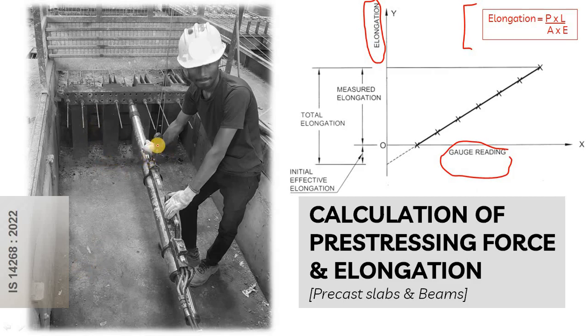Here in the left hand side figure you can see the pre-stressing gun that is used, and these are the strand wires that are used. This is the pre-stressing system in which the strand wires are stressed before the pouring of the concrete. Here you can see the wedges and barrel. We will also see in a further slide what wedges and barrel are and why they are used. Basically this is the anchoring structure. The strand wire is locked using the wedges and barrel over here, and similarly on the other end, on the back side, the same wedges and barrel will be used to lock the wire.